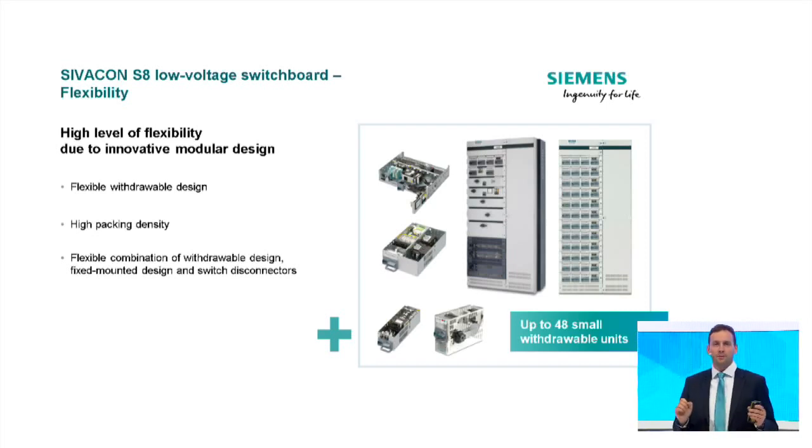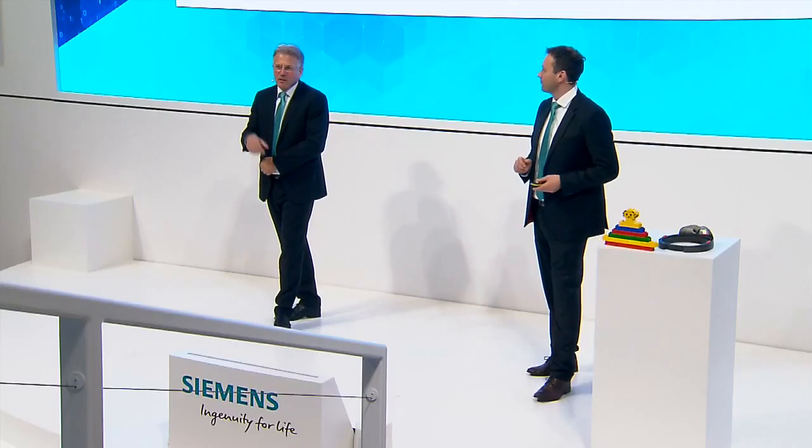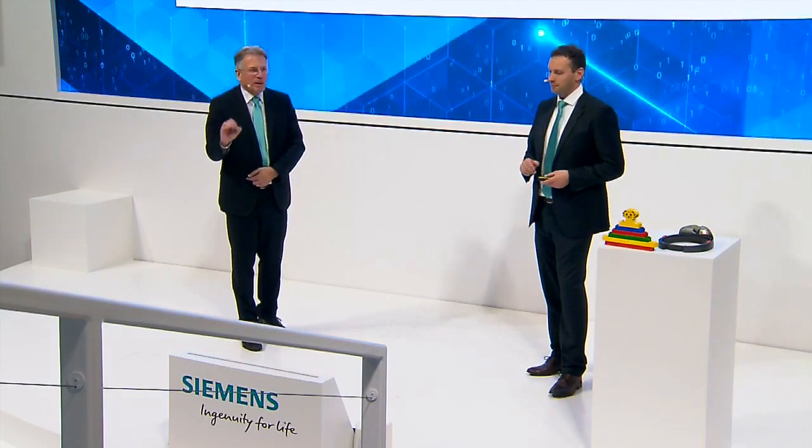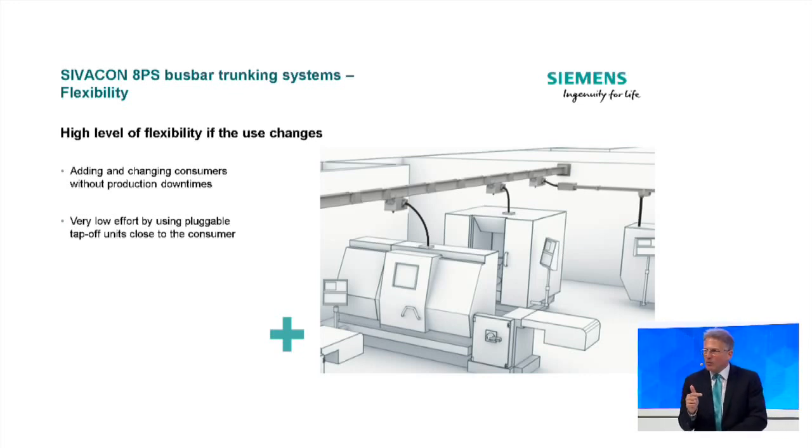Do conventional cable installations still meet the new requirement for high flexibility too? I really doubt it, because the effort in changing a cable installation and the required downtime is not accepted anymore. With a busbar trunking system, you can adapt a new machine very quickly and very easily. Because of that, our type of units can be plugged, removed, extended, replaced on an energized system. That means you don't have to switch off the busbar run, and all the other machinery is still running.